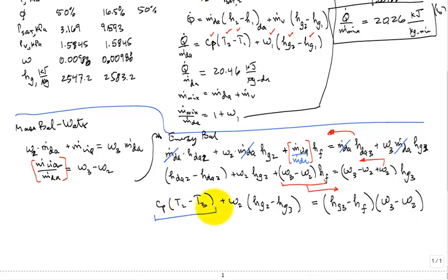What is this? Well, it's coming in at higher temperature T2 than exiting at T3. So there's a cooling of the dry air. Where does that energy go? Well, it contributes to this term over here. Well, what is this? This is the increase in the humidity ratio, and then the water came in as liquid hf and left as vapor at state 3. So this is the energy. So this is how much it took to evaporate.